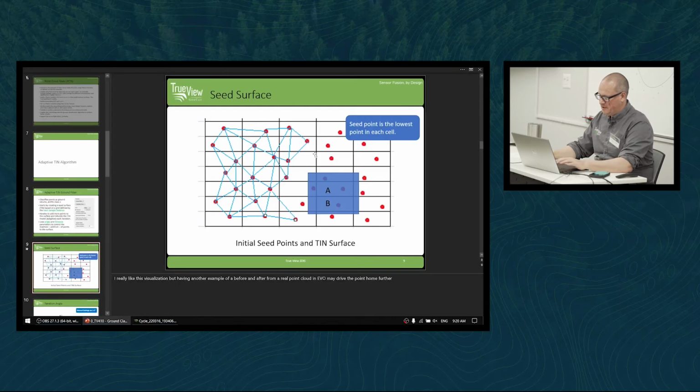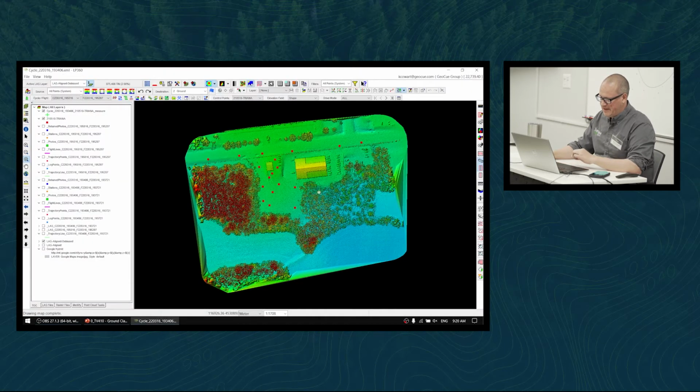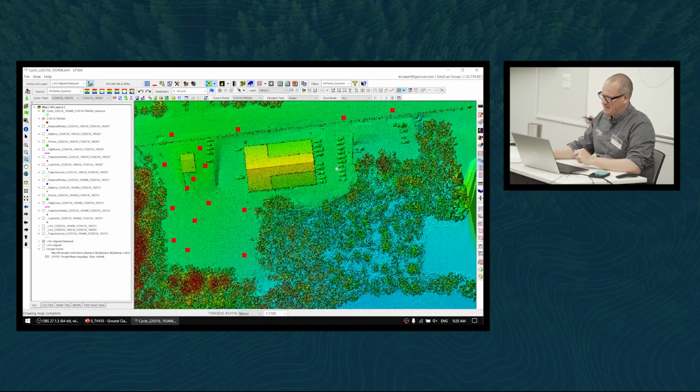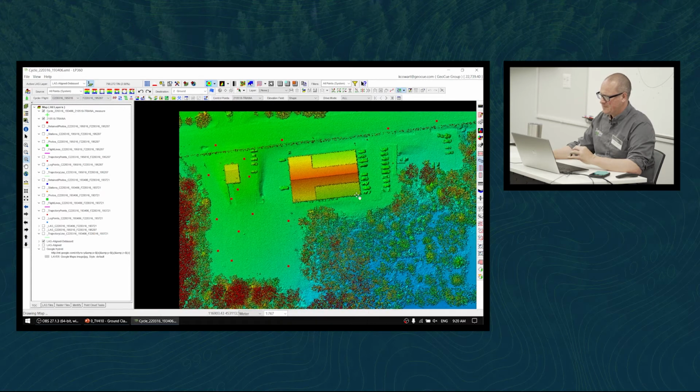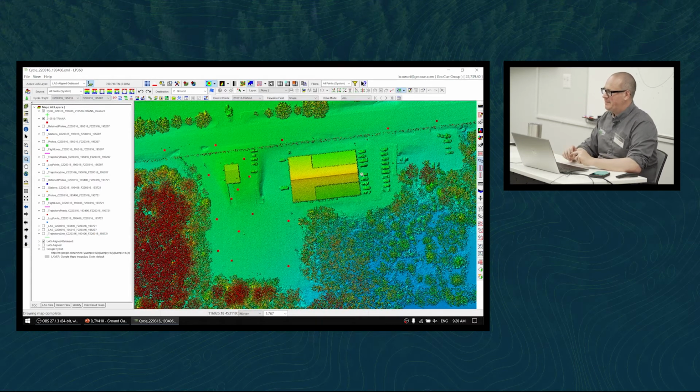Before we do that, what we want to look at is a tool called smoothing that we can smooth data sets with and get much better results from our data set. One thing to keep in mind with the TrueView 515 and 435 is this is what's referred to by some people as a utility grade LiDAR or an automotive LiDAR. It was never built with the intention of being a mapping instrument.